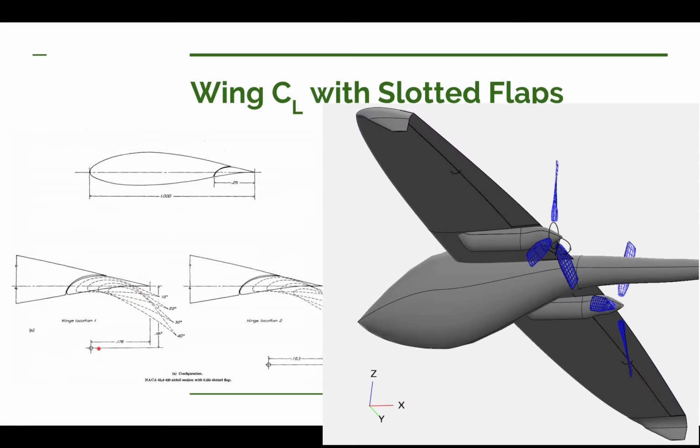Now on the UWS-1, we're going to take advantage of a couple things. We will have one hinge built into the side of the fuselage. Having this hinge built in the fuselage, then we will not have to have something sticking down from the wing. As far as the flap goes, we can fare the portion between the flap and the hinge into a recess in the fuselage so that at least in cruise there's no drag.